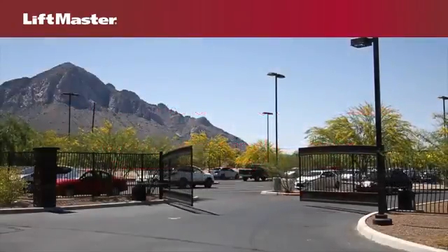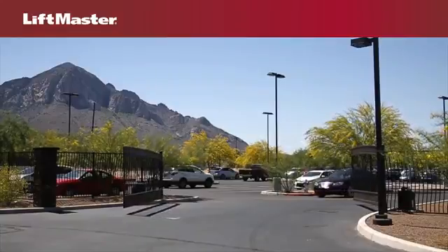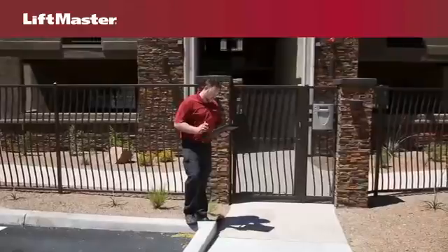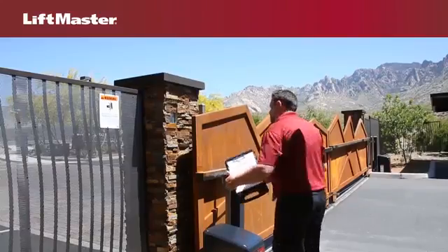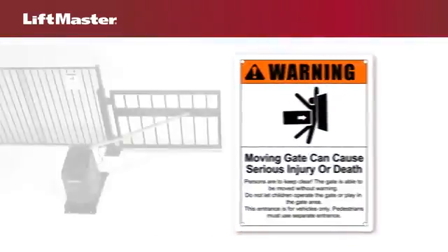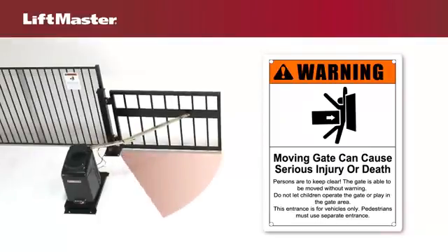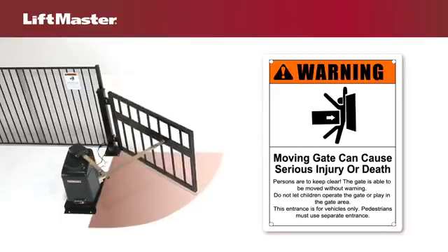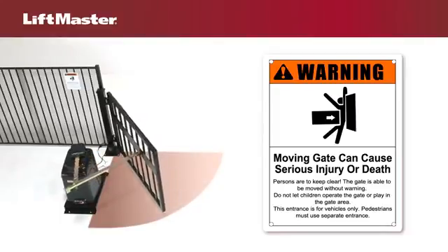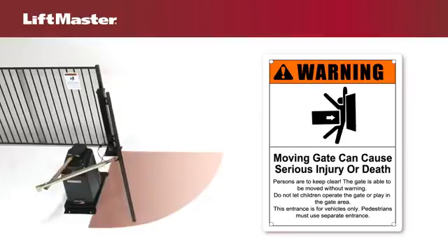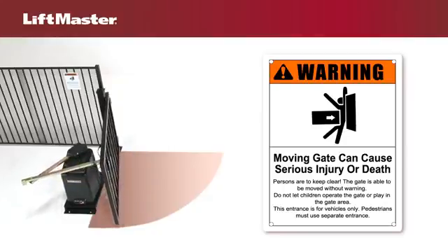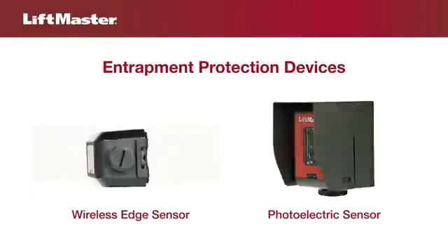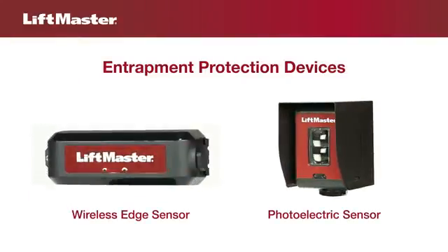When it comes to safety, keeping pedestrians and objects away from automated vehicular gates is the best practice. Providing separate access for pedestrians and posting warning signs are essential, but they're not enough. Vehicular automated gates present a risk of serious injury or death if an individual becomes entrapped between a moving gate and a stationary object, such as a post or wall. Any location or point of contact where such an entrapment can occur is called an entrapment zone. LiftMaster offers a number of product options to protect against the dangers of entrapment.